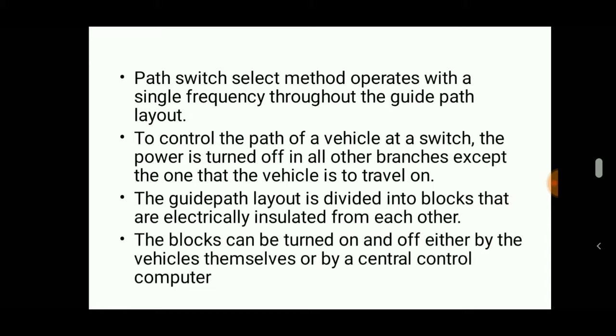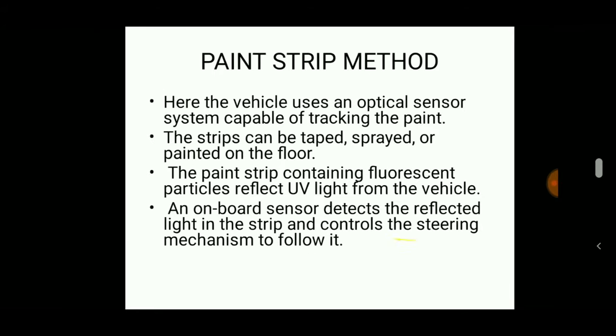The guide path layout is divided into blocks that are electrically insulated from each other because the vehicle has to follow only the selected path and not the other paths. The blocks can be turned on and off either by the vehicles themselves or by a control computer.